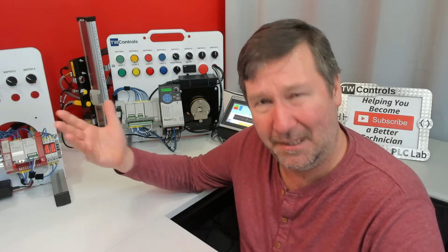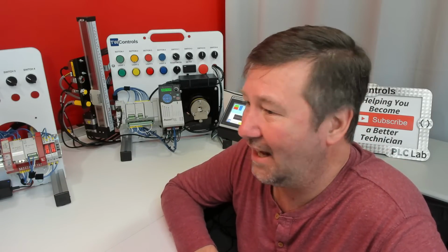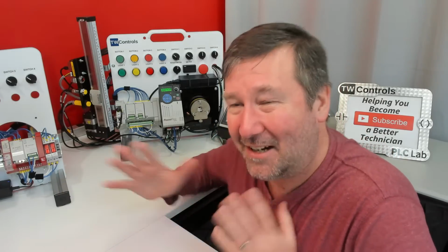I wouldn't call it proprietary because EtherNet/IP is an open protocol, and I think Profinet's an open protocol, but obviously EtherNet/IP is what Allen-Bradley gravitates toward, and Siemens gravitates toward Profinet. Modbus TCP is always the interesting one because it kind of feels like somebody dropped a paper with a specification on the way out the door and somebody made 10,000 copies of it, but nobody ever really explained it. So it's arguably the universal protocol that nobody knows for sure exactly how to get everything to line up right on.